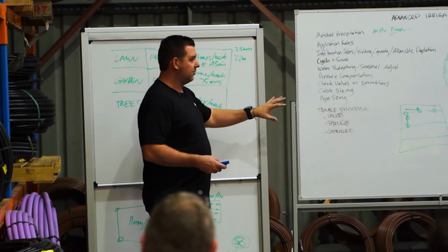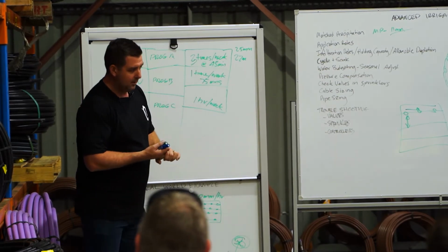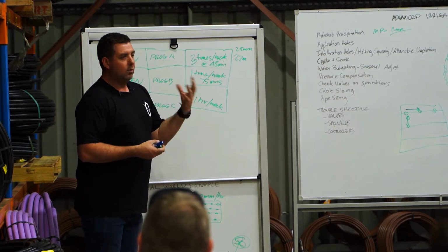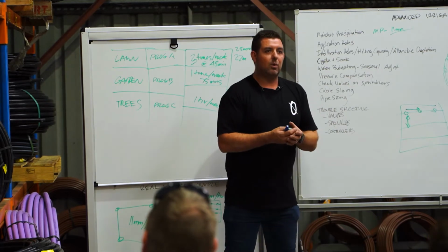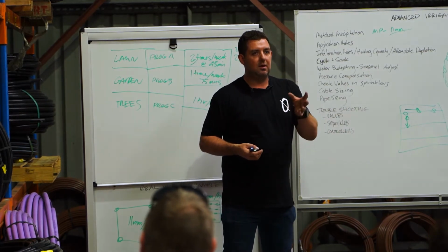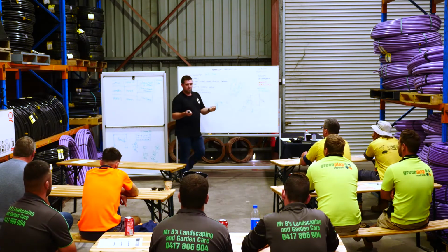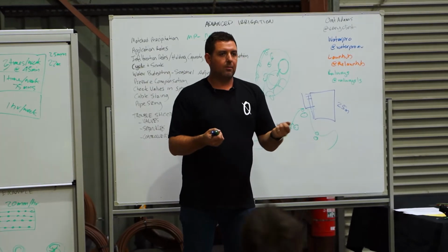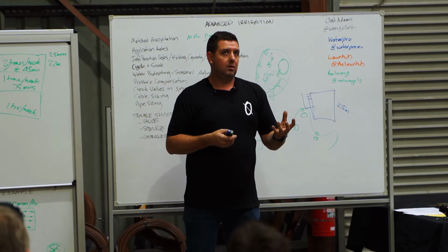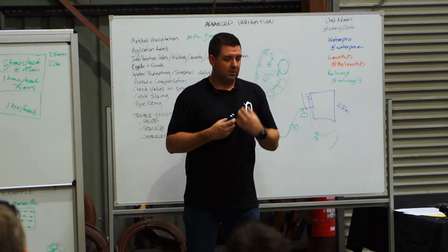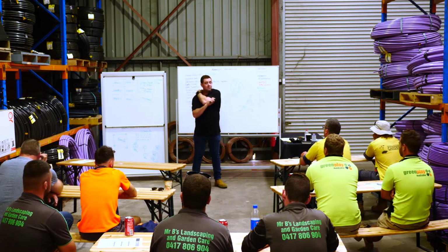All the products that we stock, the Rainbird and the Hunter and the Netafim and the Toro drip tube, they've all got pressure compensation, pressure regulation, or matched precipitation, or they've got wind tunnel data where they've tested the sprinklers in simulated situations, so that you come back with the amount of water per minute or the amount of mil per hour that's going to be delivered. Therefore it's easy for us to design a system, but it also gives you ammunition to go, well, we've actually done the calculations and this is how much you're going to need.